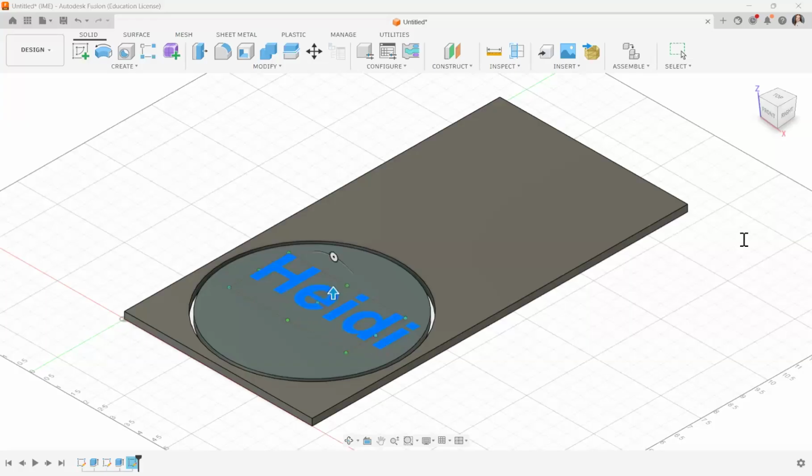So I'll tell you that if you cut something all the way through, you're probably going to break the tool bit because these shapes will be moving around inside the pocket here, the void that the machine will create. And that's just not a good thing. Also, these little parts tend to fly off the machine. So we're not going to do that, okay?